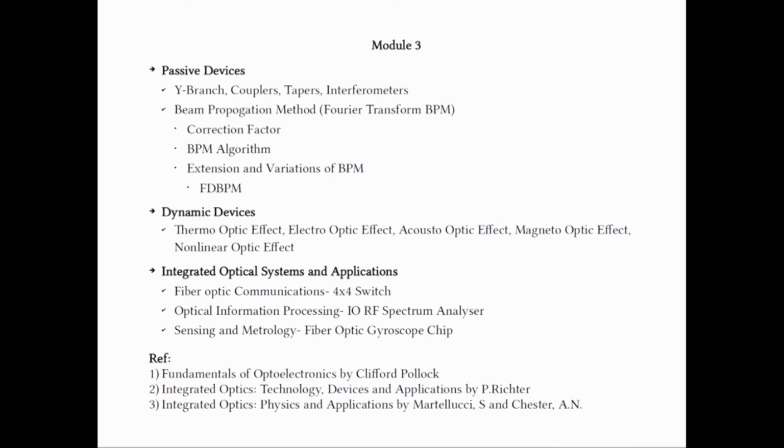propagating through these planar waveguides, and the grating is created by this RF field. The grating properties could be changed with the input RF field. Suppose the RF field contains a broader spectrum, all the components result in a grating. We can say that there is a superposition of all these gratings resulting in a particular refractive index variation pattern.